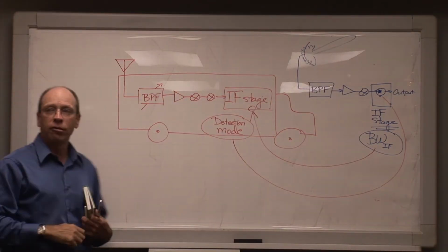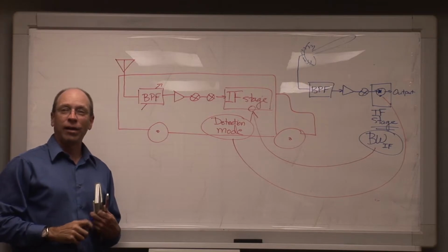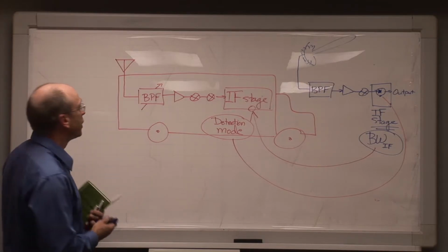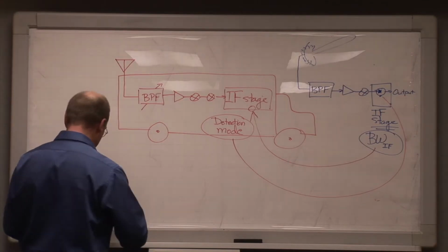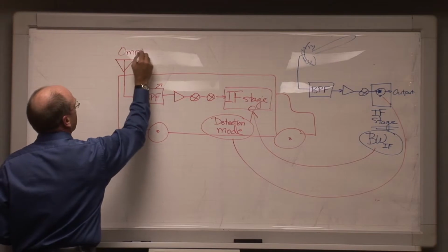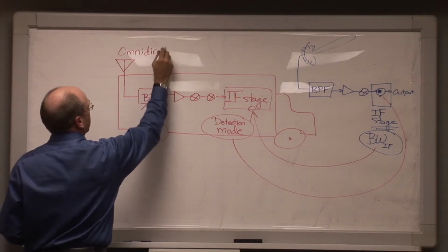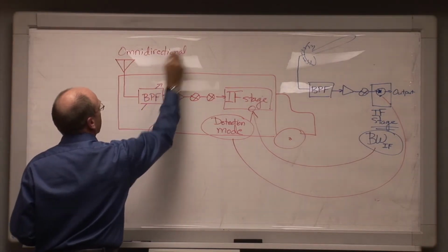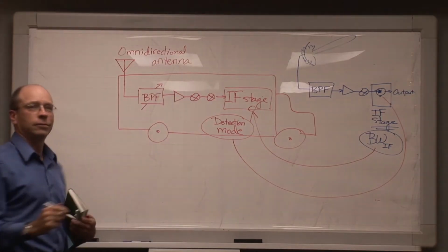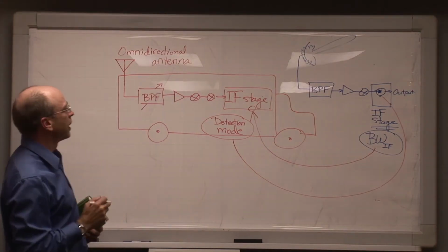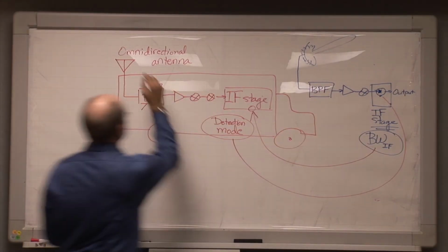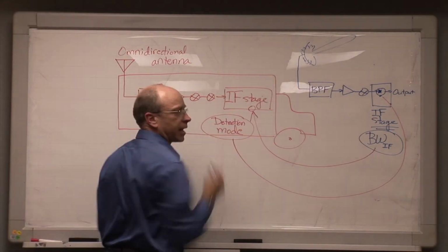Now, what antenna would we want to use? Well, we don't want to use a dish antenna. That's one thing we do not want to replicate. What we want to use over here is an omnidirectional, or as close to omnidirectional as we can get, antenna. You're probably thinking, well, wait a minute, you just said replicate the bandwidth, right? Replicate the detection mode, right? But use an omni antenna even though they're using a high gain dish?